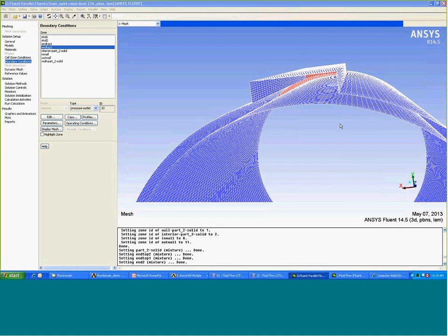Similar to the CFX. So with this in mind, if you can decompose the flow domain into a single part with multi-bodies, and Workbench is able to mesh it to give you flow-through mesh, that would be ideal. Then you don't need to worry about these interfaces at all.